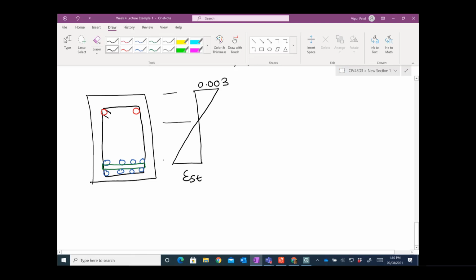And we have this depth of the neutral axis, which is the unknown value all the time. Now we have one more addition, which is this one. What is that? This is the strain in the compression reinforcement. That is an additional component. Last week we had only two strains, EST, which is the tensile, and the other one is 0.003. But in today's lecture we add one more strain, so that is going to add one more component.